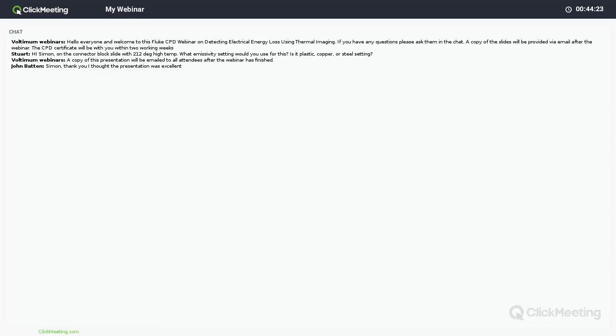When I do a more in-depth thermal imaging seminar and I'm doing surveys, I try and leave my emissivity set roughly between about 0.92 and about 0.95. And I take my measurements on the actual plastic or the insulation material, whatever type of PVC it is. When you're doing measurements on metals,